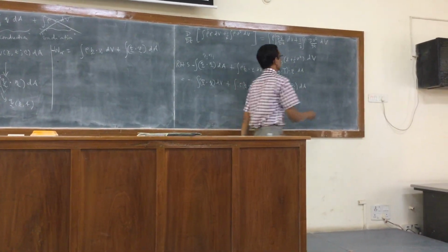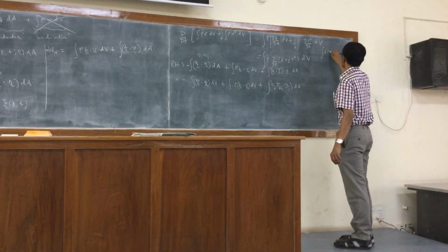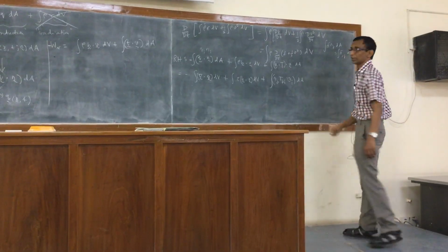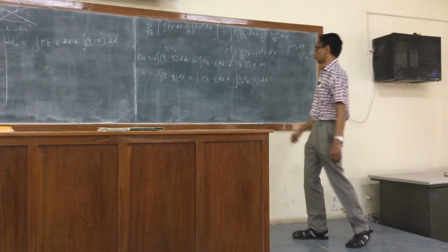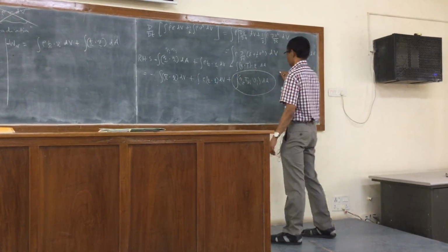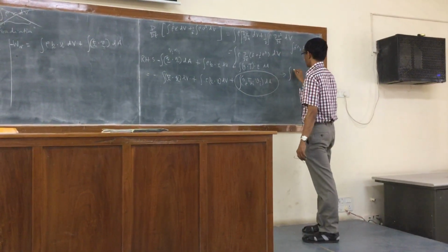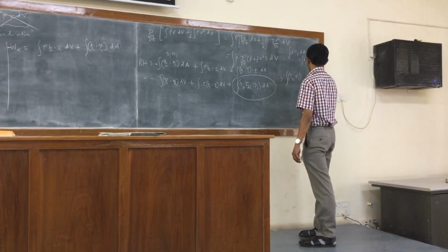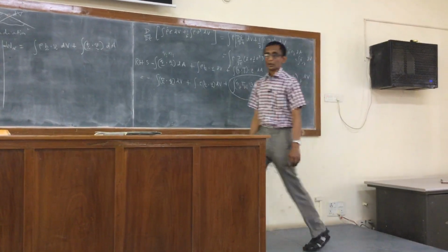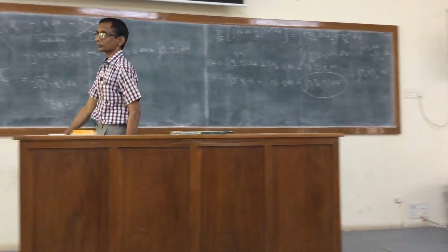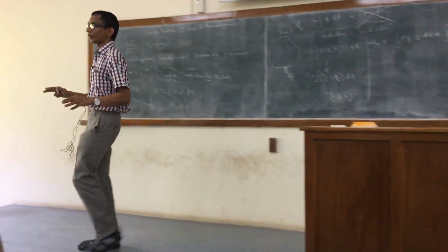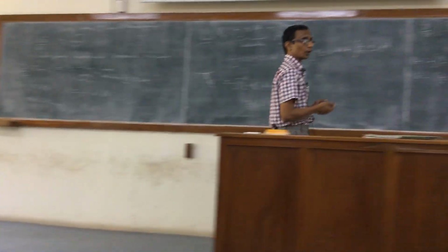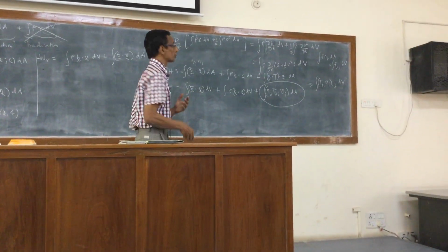So again, I will use the fact that the integral of f n_j dA is equal to the integral of f comma j dV, that very convenient form. So this whole term will simply become the integral of t_ji v_i comma j dV. So now all the area integrals have been converted to volume integrals. I can by inspection now write the local first law of thermodynamics as